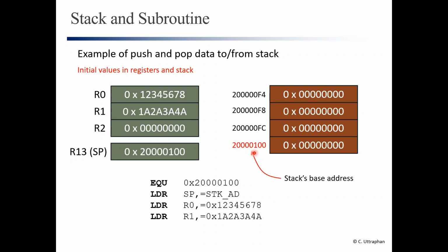Observe that the memory in this example is viewed in word format instead of in byte format as we have seen in the example before this. Therefore, the next address of the stack is hex 200FFFFC, which is hex 20,100,000 minus 4. Then the next address is hex 200FFFF8 and so forth.